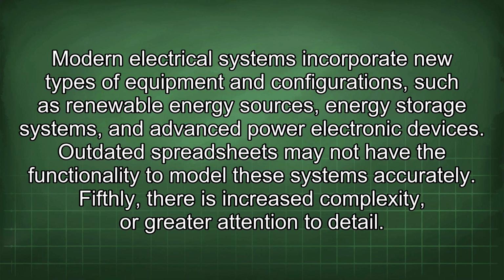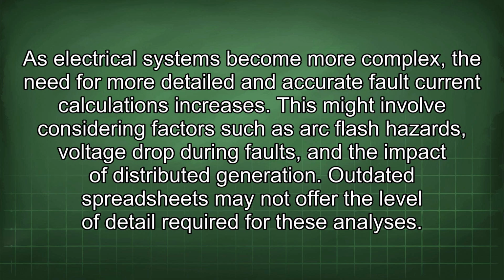Fifthly, there is increased complexity or greater attention to detail. As electrical systems become more complex, the need for more detailed and accurate fault current calculations increases. This might involve considering factors such as arc flash hazards, voltage drop during faults, and the impact of distributed generation. Outdated spreadsheets may not offer the level of detail required for these analyses.